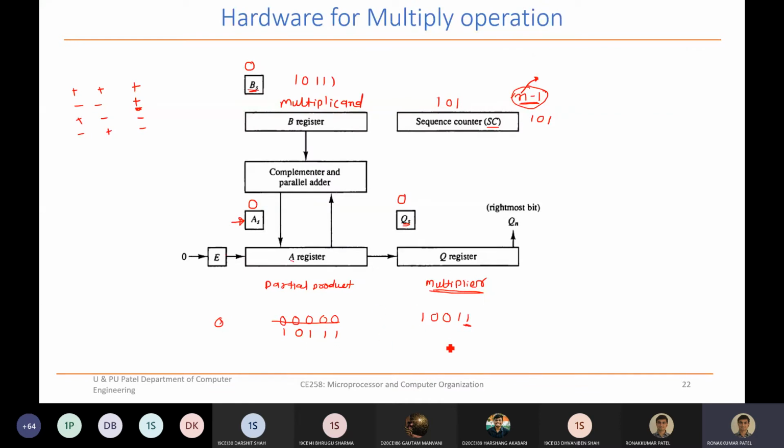So when you perform the shift right operation, what happens? This least significant bit will be discarded because it goes out of the register. So now 1 0 0 1. Shift right. This is the empty position. So this will move to that empty position. 1. Okay. And now 1 is moved to this. Shift right 1 bit. So we are shifting right with 1 bit. So here 1 1 0 1.